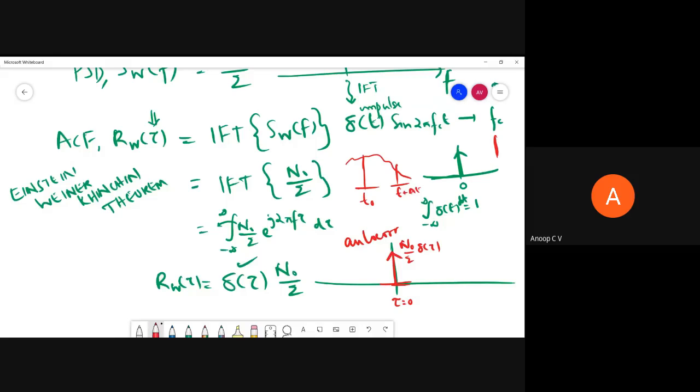So when you studied signals and systems, you might have studied deterministic and random signals. So this white noise process is a completely random thing. Any two samples, however closely spaced they are, or however largely separated they are in time, will not have any correlation. It will be equal to zero. A sample will have correlation only with itself. This is one way of defining it. So we'll use it for all the cases.